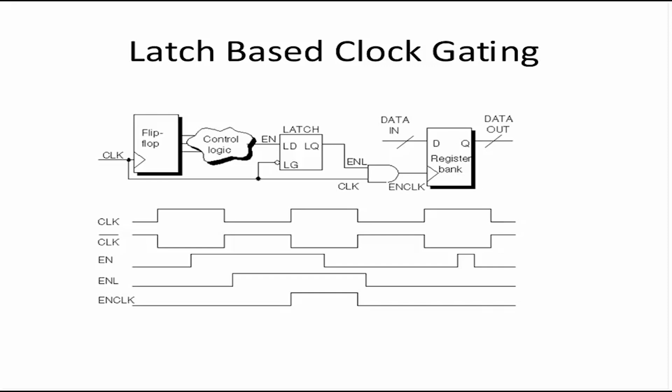You do not want that. So for such type of AND gating without a latch, you can draw it on paper and see that without using a latch, for the AND gate and OR gate both, the enable signal is free to toggle at any time, right? So you have a lot more restrictions on EN, the enable signal. If it toggles during unnecessary time, the clock edge can get clipped off. We do not want that. So that is why we use a latch.